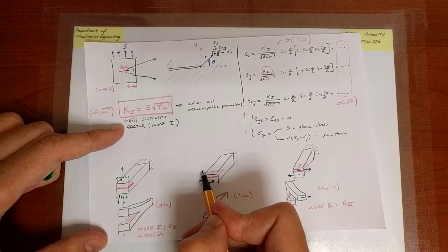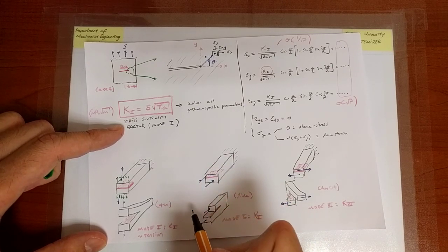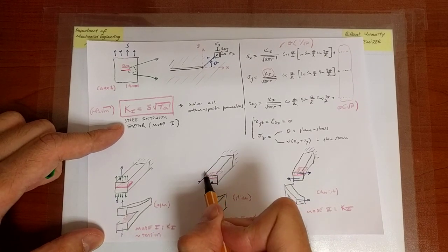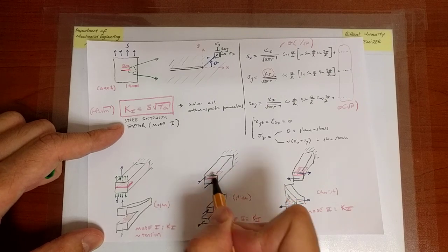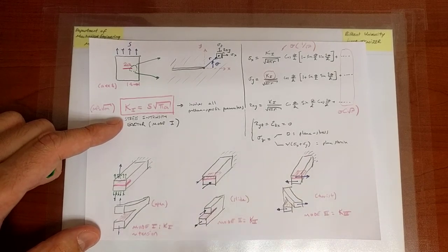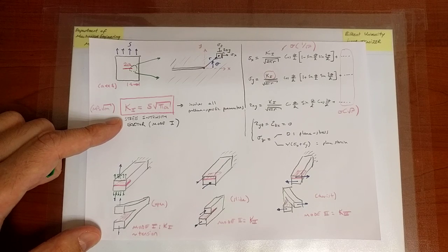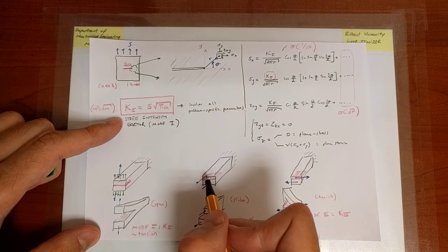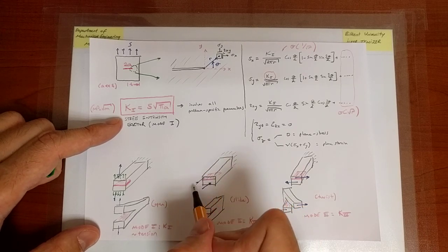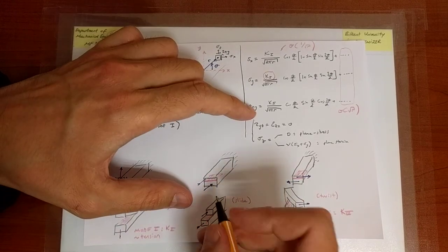But ultimately, over the whole surface, what would be the statically equivalent representation of that stress distribution? Or for that matter, what would be the statically equivalent representation of this, a set of two forces, or for this couple, to give you a hint? And similarly, in this case. Okay. Now, if you've taken a minute to think about it, you can see that the statically equivalent representation of this distribution is a moment in this case.